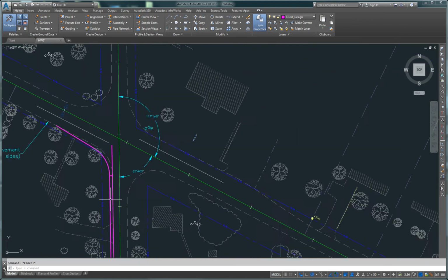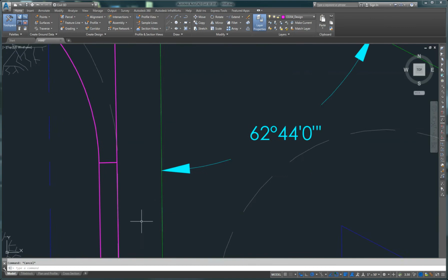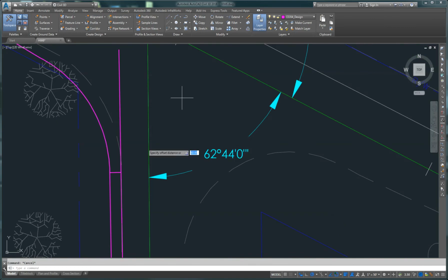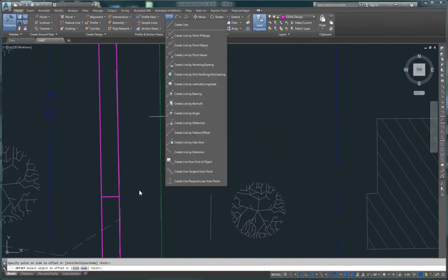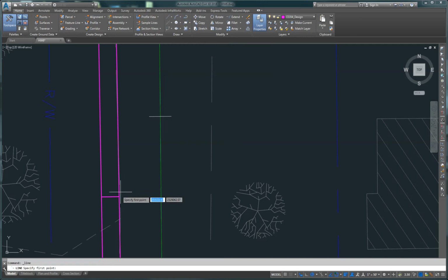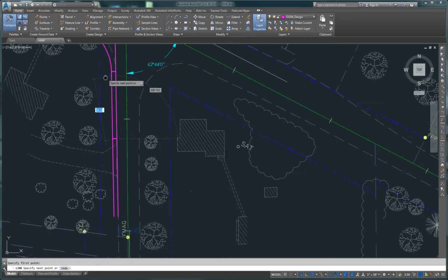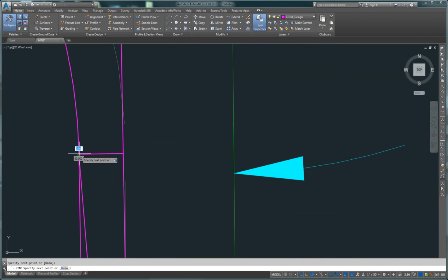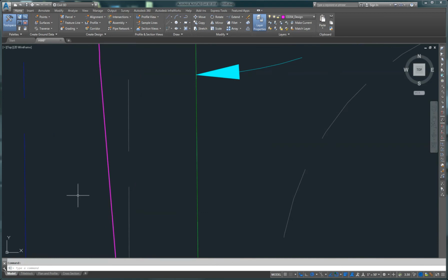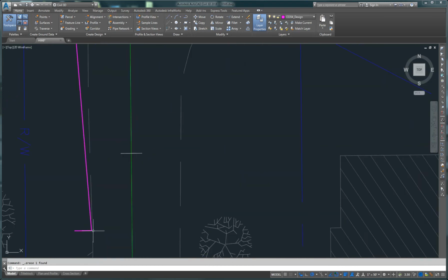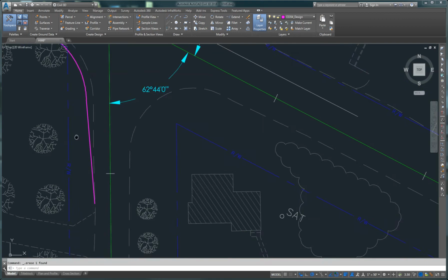And on this side here, since I haven't drawn in my taper yet, I'm going to start at this point. I'm going to offset this to 60 feet I needed. Type in 60. Grab him. Click on that side. Now I've got my other line down here. Connect those lines together. This is the quicker way to do it. Starting here at the shoulder and coming back up here and snagging the end of that arc. There we go. And now trim off all the excess. Delete them. Just click the line and highlight it and then hit delete. There we go. And I got one more here. Trim off. Gotcha. All right.